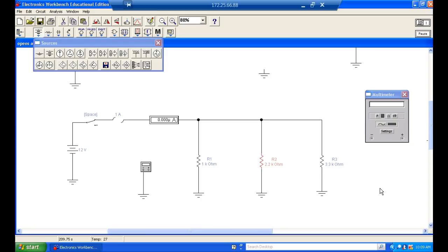And my breaker pops. But it popped at 15 amps, but I put a 20 amp breaker in there and it doesn't pop anymore because the R is still there, right? You understand? Now my house burns down. Because I had a circuit breaker that was popping all the time, and I went down to Lowe's and bought a 20 amp breaker to keep it from popping. And my wire's rated at 15 amps.